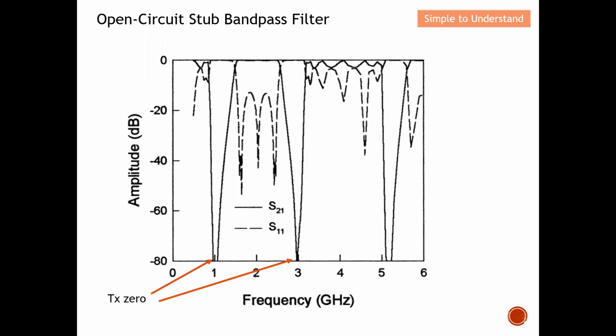However, as I told you earlier, I can have a steeper roll-off factor. I can also escape the via. So you can also consider using this open circuit stub if you have another band stop filter to remove these two. If not, you can also consider using a short circuit stub. But in this video, I mainly concentrate on the open circuit stub design.